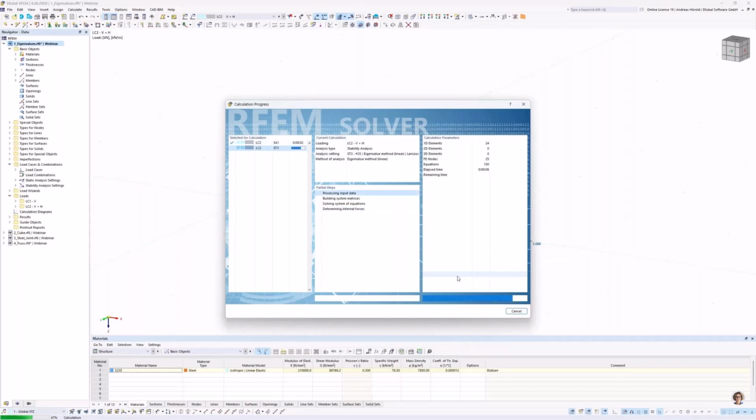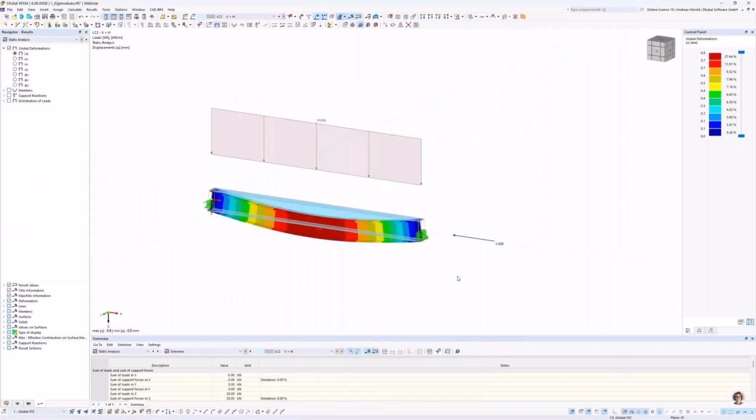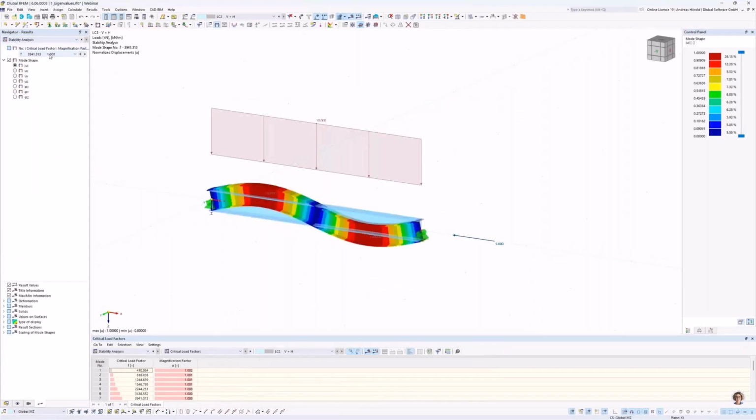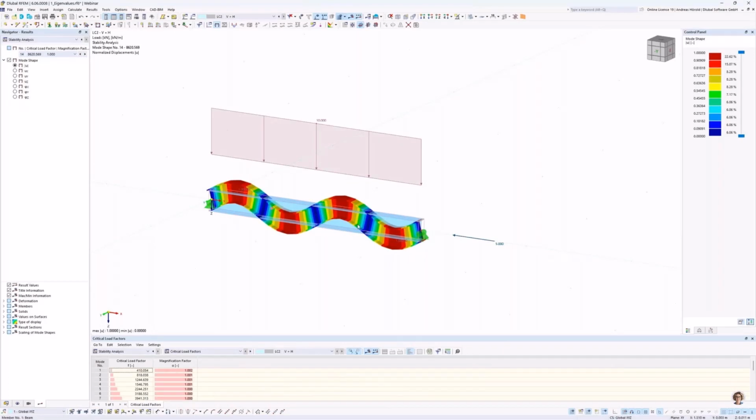Here, as in any FE calculation, let's go through the eigenvalues. Those eigenvalues look quite a bit better. And here, as in any FE calculation, the principle applies that the FE mesh should be kept as coarse as possible, but at the same time as fine as necessary.